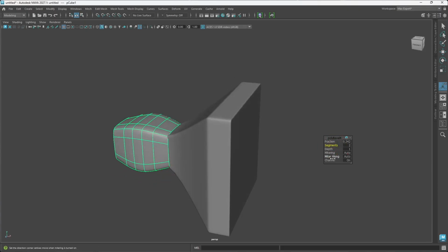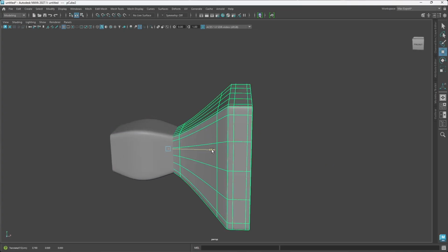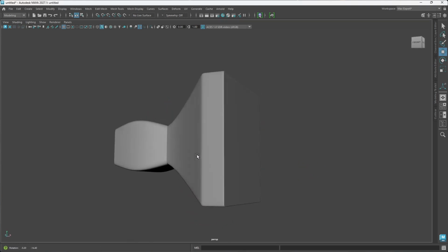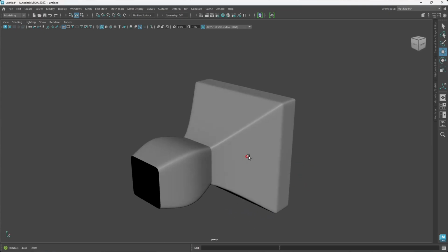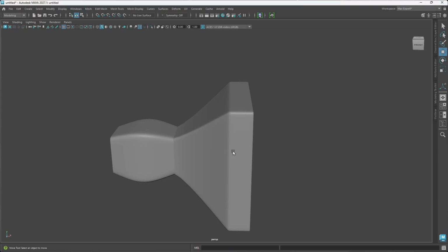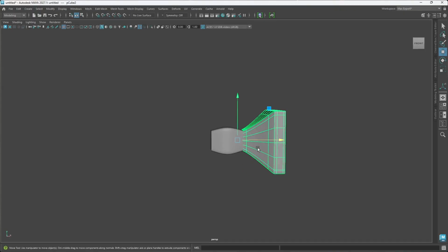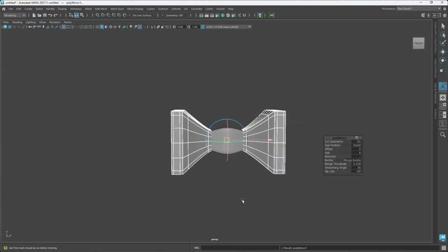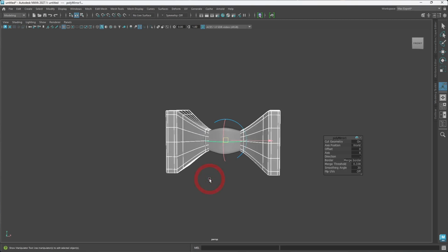the bevel. So let me turn off chamfer. Okay. Now this is okay. So we can bring this backward and close that space right there. We just have a little space that can also work. We can leave it out. Okay, now we need to move this over to the other side. Now you can duplicate, rotate, and do it. That is fine. But the quickest and easiest way to do this is just selecting the object, shift right click, and going to mirror. Now, when you mirror, it just mirrors it here exactly as you want it. So you can continue with that.